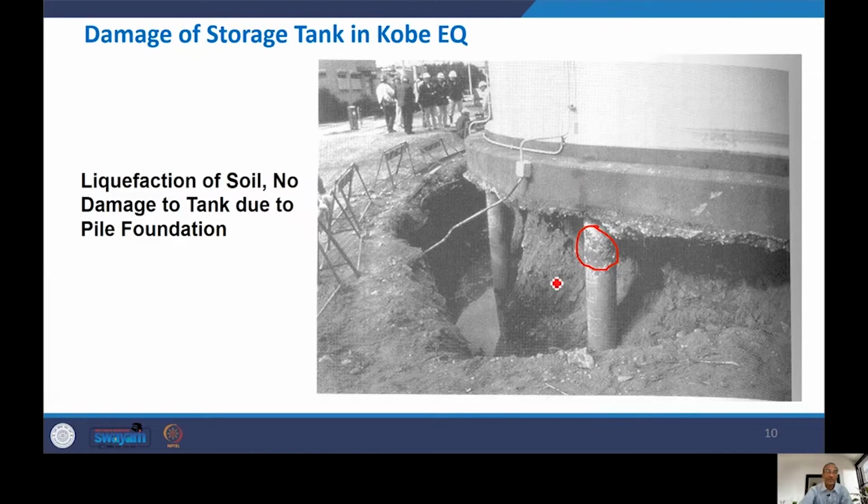So there is only small damage, small cracking of plaster and other things on the piles, but they are safe, they are working. There was no damage to the superstructure. So that means due to this pile foundation, this structure survived. Continue with that.